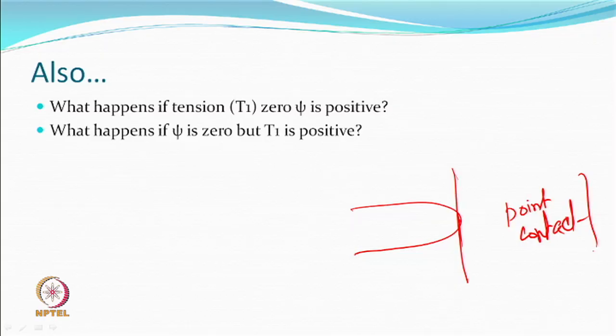Therefore, in friction texturing, and the kind of friction texturing we are talking about, the tension and psi, which is the angle of wrap, have a definite positive role, and whenever they change, something will change. The amount of twist will change because of tension itself. So, even if you do not like it, twist gets inserted, because contact will be more. Therefore, the torque is going to be different, the external frictional force is going to be different.